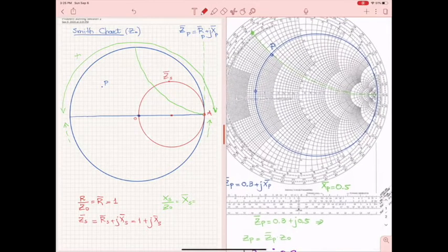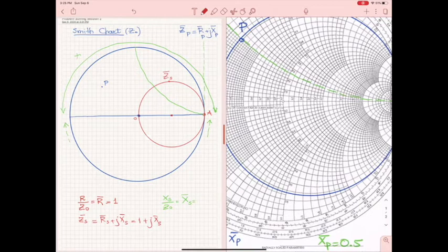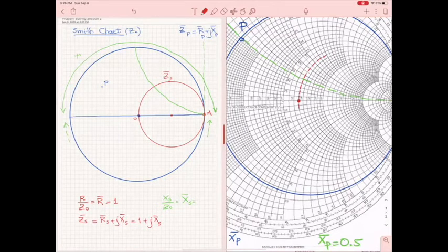So I look where the values of 1.3 are on the Smith chart. All of the points of the circle that go through this 1.3 point, a constant resistance circle, have the same normalized resistance, 1.3. I'm not going to draw all of it; I will stop here somewhere.